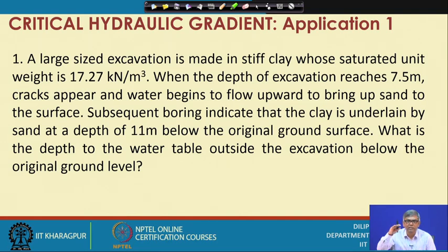Initially excavation is going on and there is no water visible; it is saturated or partly saturated. But when it reaches a certain depth, the bottom cracks appear and sand boiling type of effect starts. That means there is some pressure from the bottom.